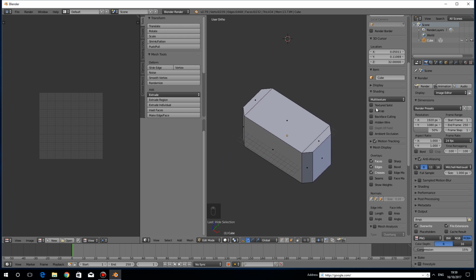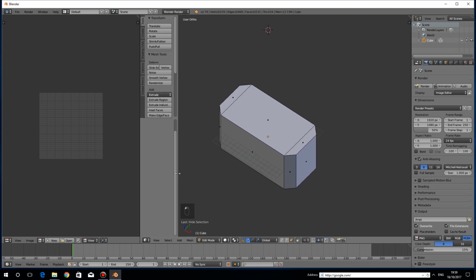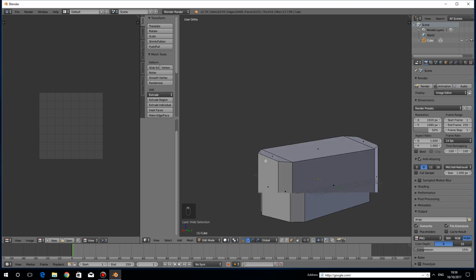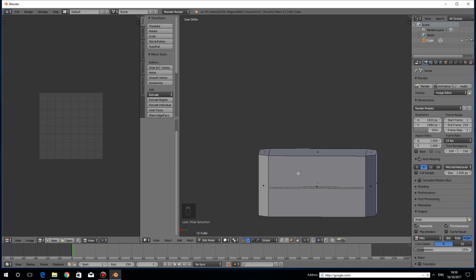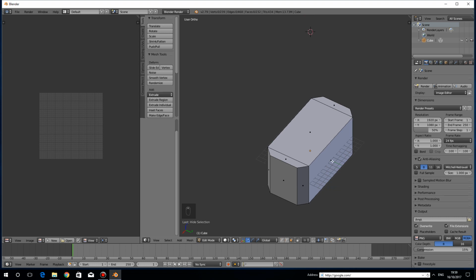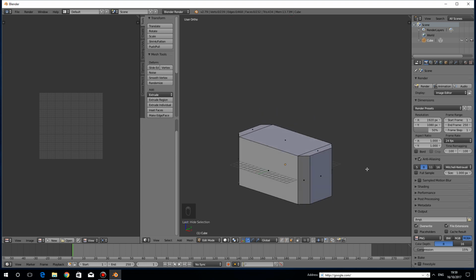Right, I'm going to close this menu by pressing N, and just drag that in a little bit. Right, okay. So what I want to do is unwrap this so that when it's displayed on the UVs, it's like a cardboard box has been folded out. One piece, but expanded, exploded. So what we need to do there is select edge,